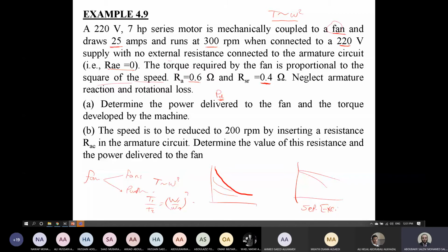We have the relation of resistance R equals rho L over A. If we have a high cross-section, the resistance will be small, and this is an indication that you can flow a high current. However, if the cross-section is very small, the resistance will be high, and this can support only small values of currents.